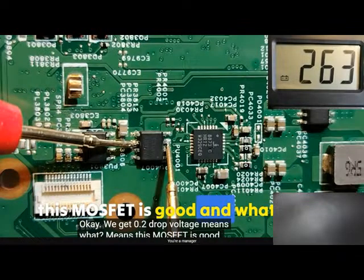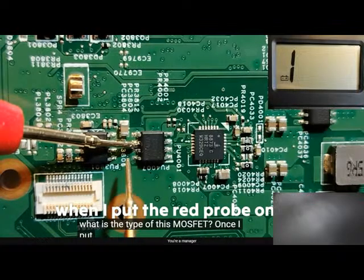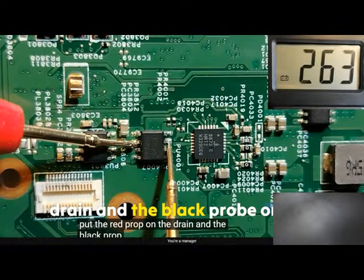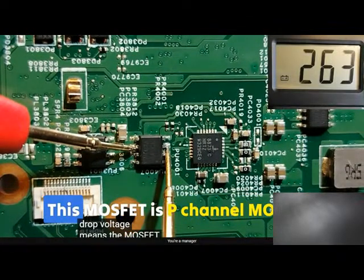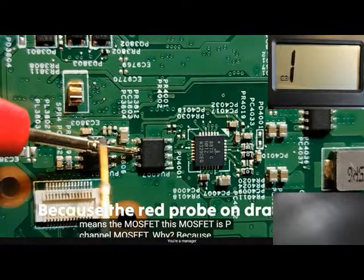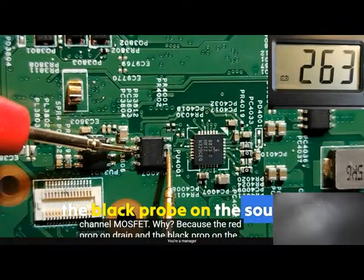And what is the type of this MOSFET? Once I put the red probe on the drain and the black probe on the source, and I get a drop voltage, it means this MOSFET is a P-channel MOSFET. Why? Because the red probe is on the drain and the black probe on the source.